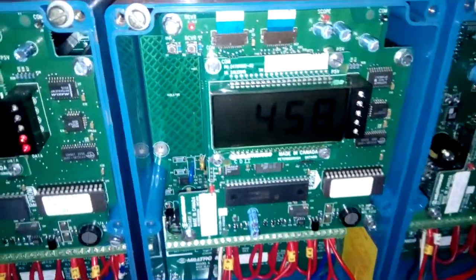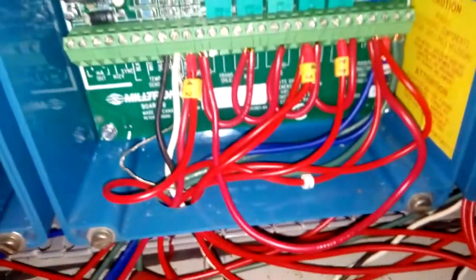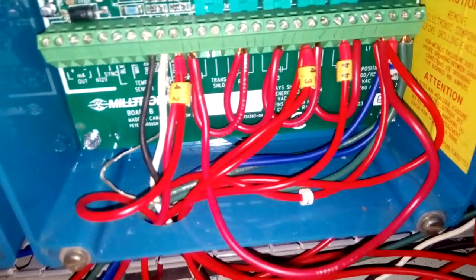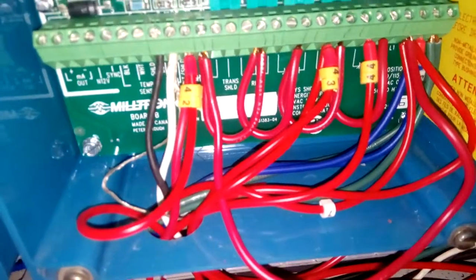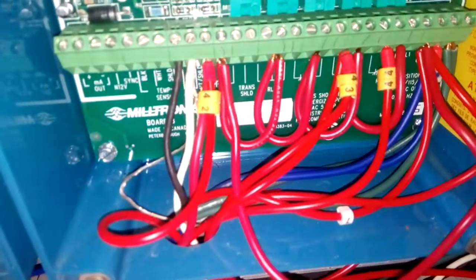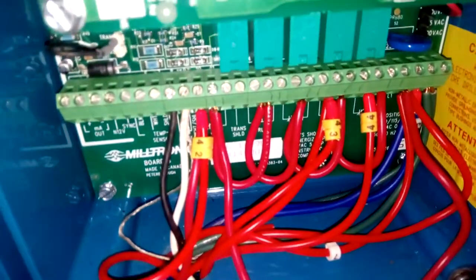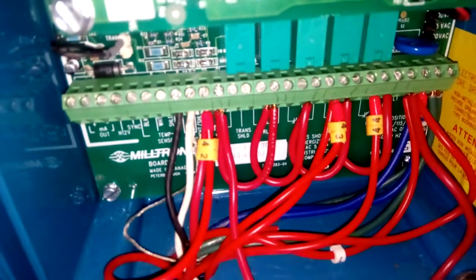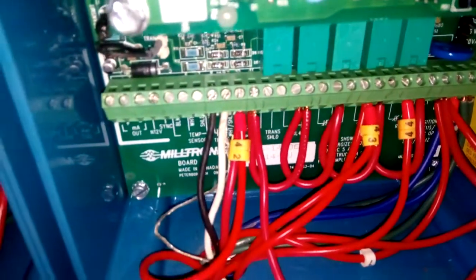So here we have the ultrasonic level transmitter. We have two signals from it, the signal cable number 43 and cable number 42. 43 is for the low level and 42 is for the high level when it's full. So we'll be using 43 for triggering the starting of pumping at the pumping station and 42 for stopping pumping